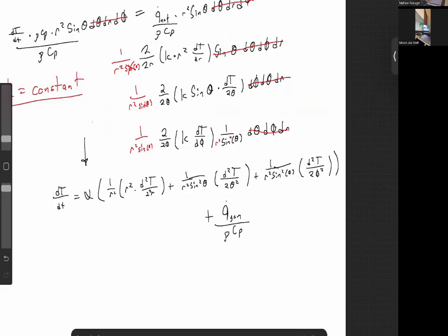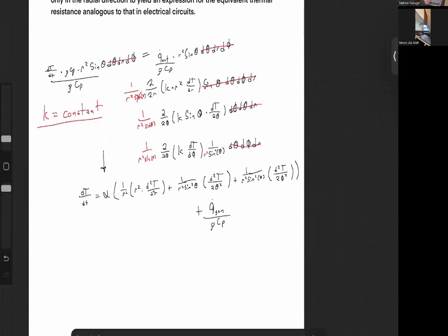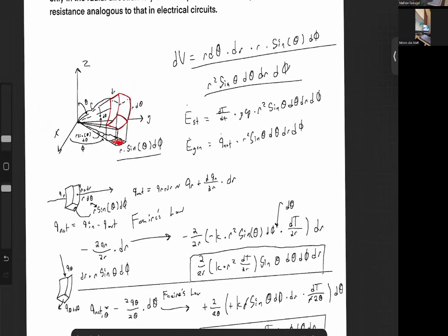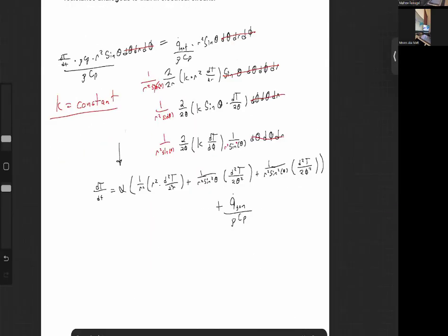All right, so that took a lot of simplifying, but essentially this is the same type of heat diffusion equation that we've solved for, except now our double derivatives are in terms of a spherical unit that we have solved for, as seen over here, with every direction accounted for, and we had to make corrections for theta and phi for them being in radians and arc length respectively.